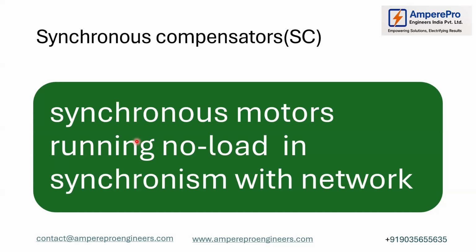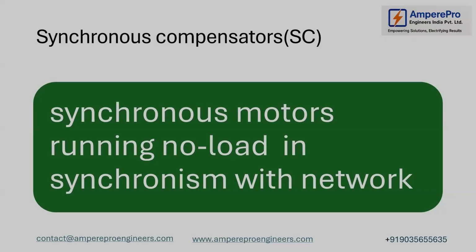Most of the time this comes in grid level projects only, to support reactive power at grid level. When you run this, you are injecting reactive power into the grid. This is the synchronous compensator, sometimes called a synchronous condenser as well.